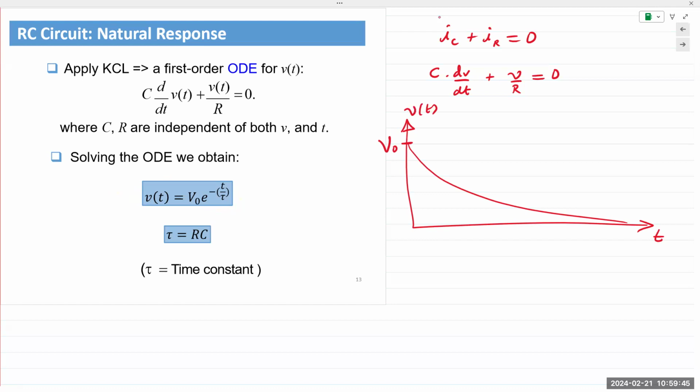It's a product of the resistor and the capacitor. So for an RC circuit, time constant tau is RC. That's it. For RL, it's L over R. It might take you a few seconds to remember that, but for RC, it's rather straightforward. And time constant remains the same for charging as well as discharging. That does not change.